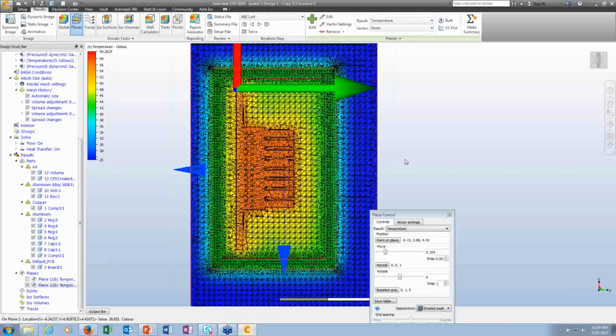And one last thing here, sometimes I see people using refinement regions on the heat sinks to get two elements in between the fins. And I don't really like that approach because you use a rectangular box and you end up really over meshing the metal fins.